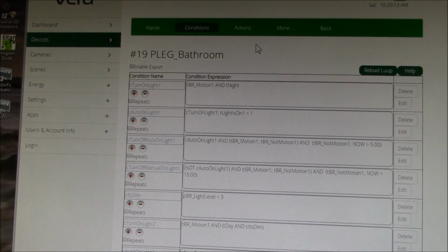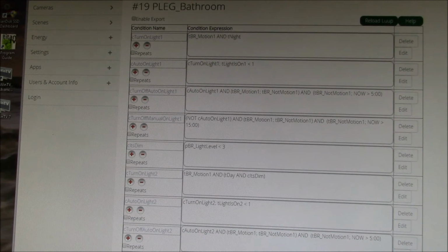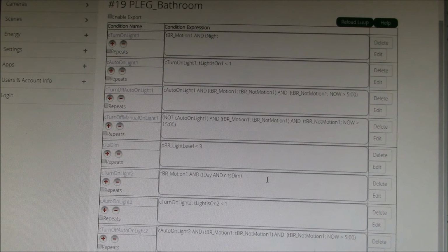And then next you define some conditions, and this is the logic that you want to use to control the various devices. In this case I only have the lights working. So with the unit I wanted to get, the automated fan, the logic was that the CFL ceiling light came on with any motion and the 4-watt night light was on all night. I wanted to improve on that so that the ceiling light only came on in the daytime and when it was not sufficiently bright enough to see without it.